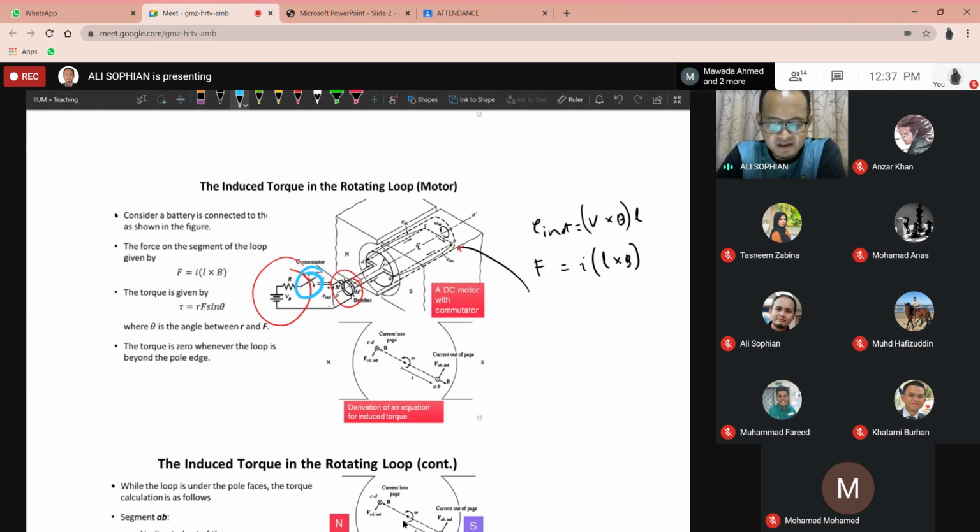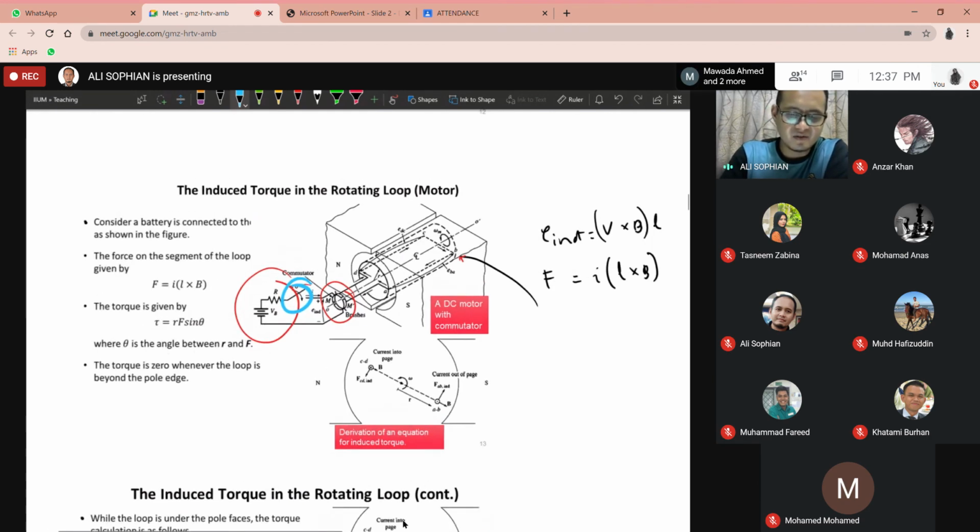Before we didn't have this. Now we have all this battery. And the R, the resistor, represents the resistance around all this path. The path means that if I can draw it, current can flow like this: from the battery through the brush segment and then to the loop, going around the loop, and then the current will come back to the battery again, from the terminal side.